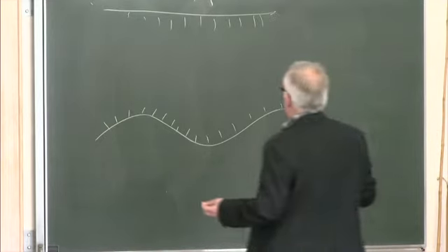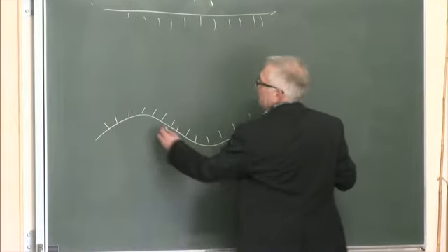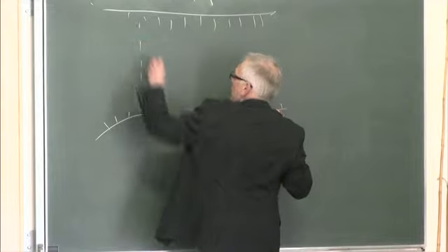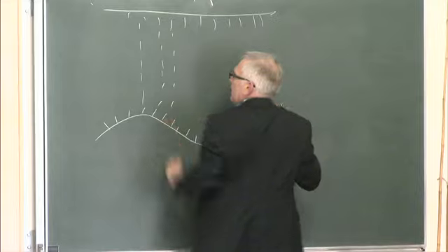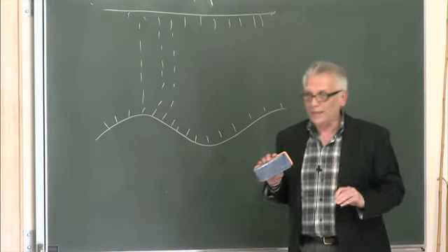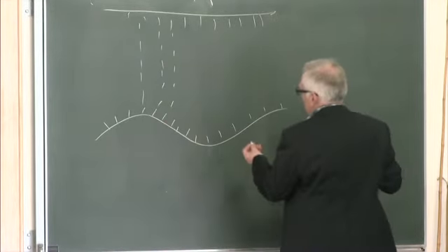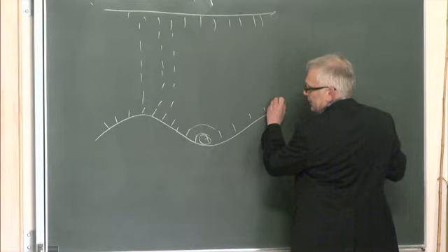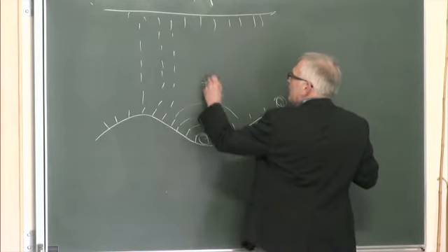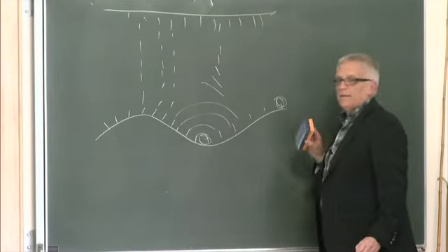We get bistability. There are two possible states. One, which is just where the liquid crystal is largely vertical. It's matching the boundary conditions, but largely vertical. That gives a dark state or darker state. And the other one, where the liquid crystal, actually there are defects. There's a defect here and a defect at the surface here, which stabilize the state, which then tilts like this.